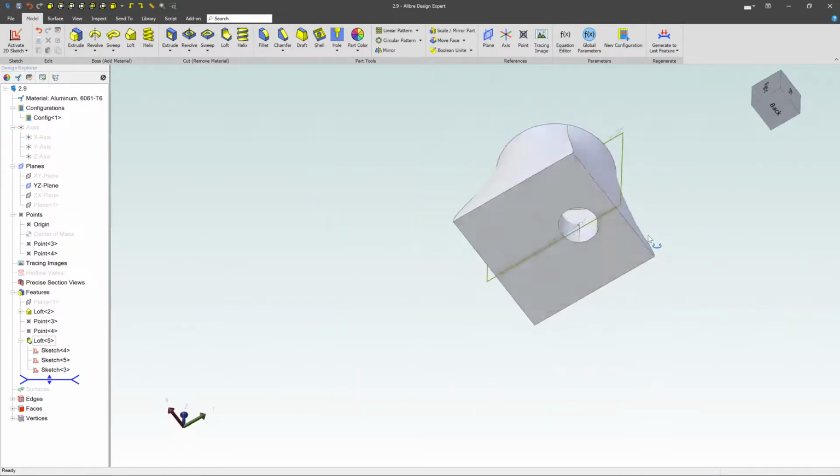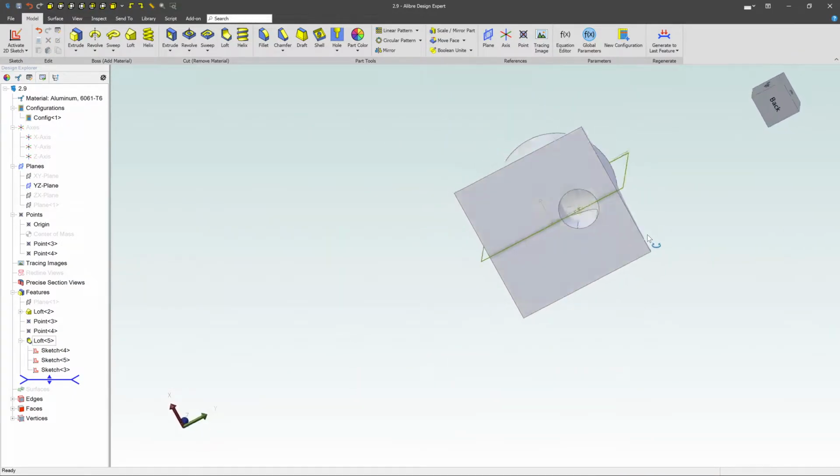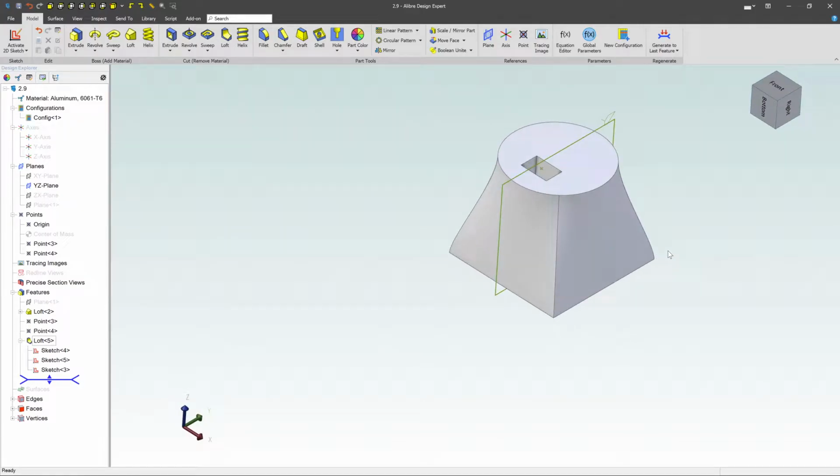So there are some steps involved, right? To do these kind of lofted features, you have to have multiple sketches on different planes, and you have to really spatially think about how everything's lining up together. And if you do need to, you can also relate reference points from one sketch to the other, like put the center point or add a dimension, things like that. So lofting and sweep features do take a little bit more forethought on how you want to create it, and you might have it fail a couple times first. But again, just remember, you've got to have a profile on the top, profile on the bottom. It's a great thing to be able to use, and it's a very powerful feature inside the software.